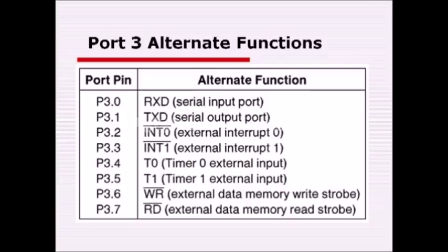So if I want to use any of these port pins as output, then those port registers should be initialized with zeros. If I want to use any of these port pins as input, then those registers should be initialized with logic 1s. And the same registers are going to hold the data when we want to transmit to or receive from the external peripherals.